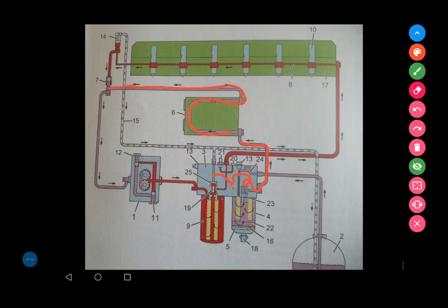to the overflow valve. Here the fuel from the tank is mixed with the return line and continues to the suction side at the feed pump. The feed pump pumps the fuel via the filter head and primary filter into the cylinder head's fuel channel number 8.